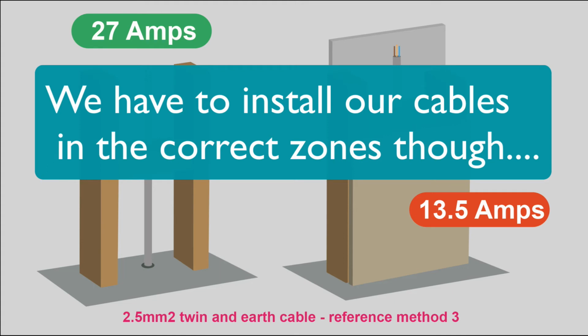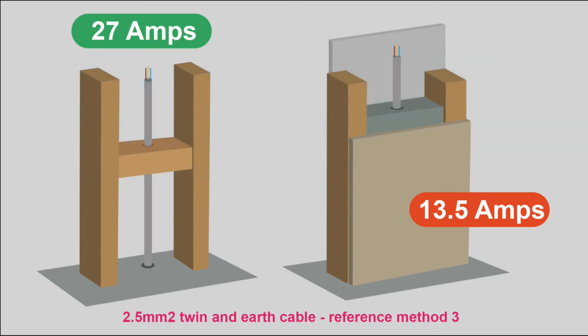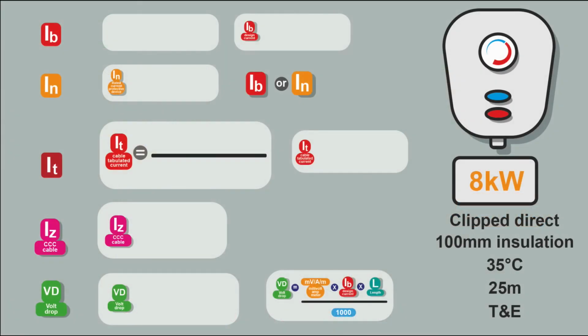It's not so onerous on the cable, but then we have the problem that we're moving the cable away from the centre of the joist where we like it because it's nice and protected. We're moving it to the edge, touching the plasterboard wall, and there's a possibility that when the plasterboard gets put on, somebody puts a screw through it. So insulation can cause real problems on a practical level, installation-wise, and also with its thermal issues. So real good care needs to be taken when you're installing a cable in stud walls. But anyway, let's get back to some cable calculations.